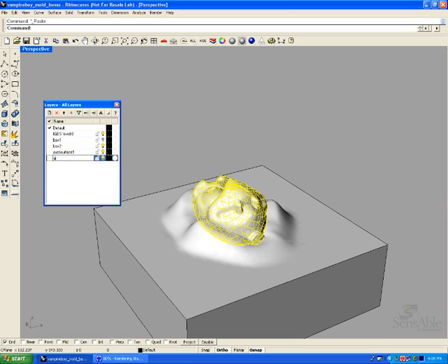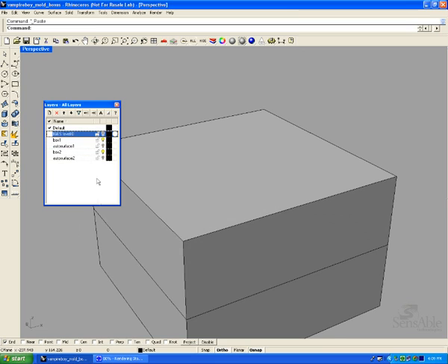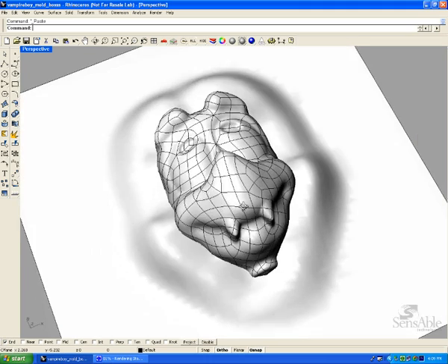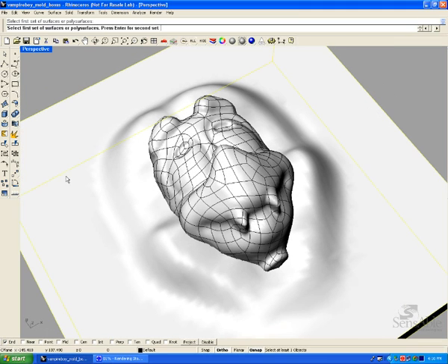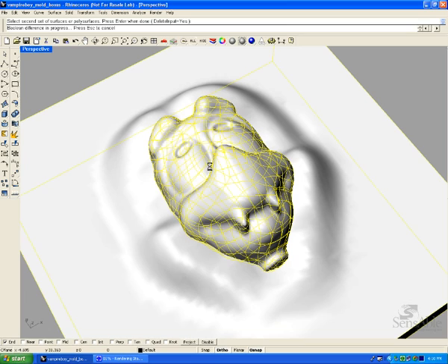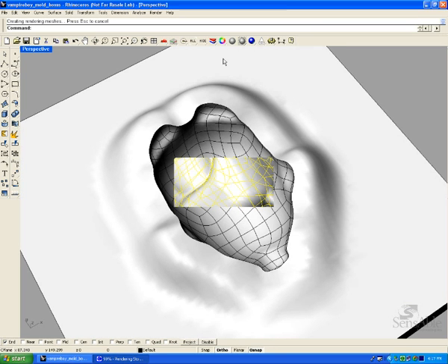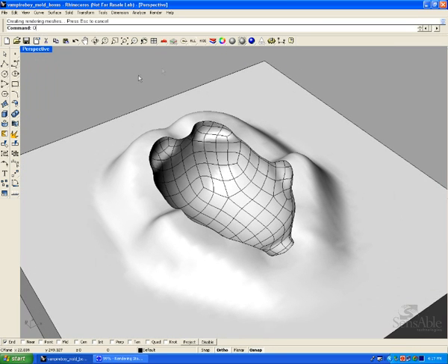And what I'm going to do is I'm going to take this positive piece and I'm going to Boolean subtract it away from the first insert block, so that once I get the two booleans, it will give me a negative part for the mold, and the intersection between the positive part and the insert block will give me that perfect parting line edge along the parting surface, the complex parting surface, which I created within FreeForm Modeling Plus.